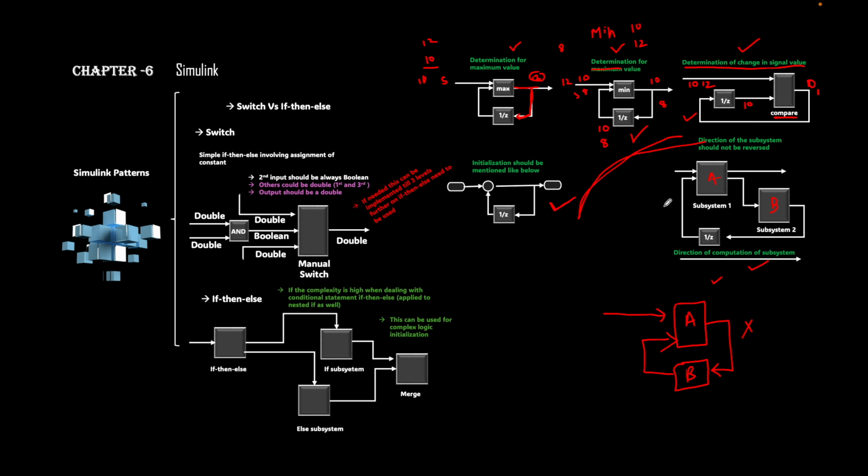In this case, what is actually being said is, suppose you have a subsystem over here, whatever the next subsystem is, that should be ahead of the current subsystem, as it is receiving the input, and then from this subsystem you can take the output and put over here. So that should be the design of subsystems in a unidirectional way, and the directions should be fixed. Even if you compute any signal as a feedback, it is a good practice to have a subsystem with proper directions, so that it will be easier to trace from which subsystem the signal is going in which direction.